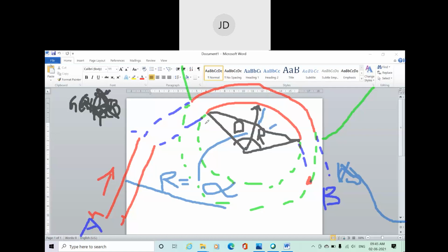And what is the basic difference between transition curve and circular curve? In the circular curve it is a constant radius, okay. That means even here also it is the same radius r, here also everywhere it is radius r. But for a transition curve, suppose there is a particular center, the radius will be gradually decreasing till it reaches the value r. So it will decrease from infinity to this r, what is r dash, whatever it is, okay.